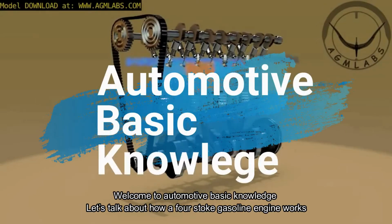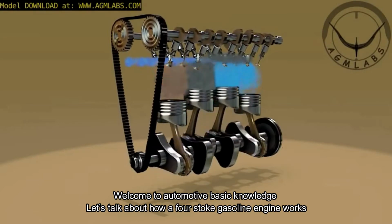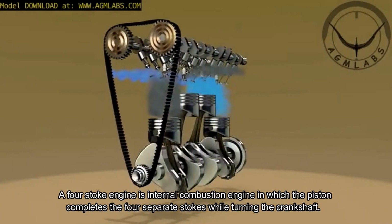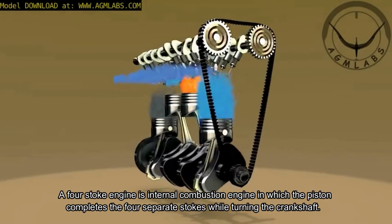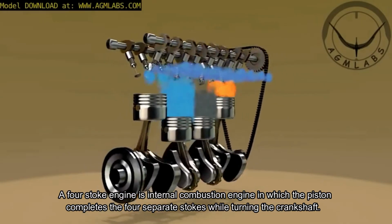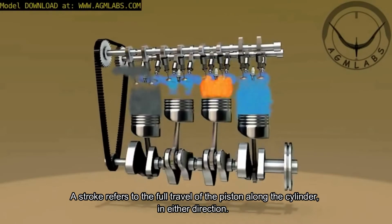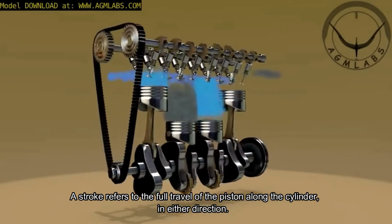Welcome to Automotive Basic Knowledge. Let's talk about how a 4-stroke gasoline engine works. A 4-stroke engine is an internal combustion engine in which the piston completes 4 separate strokes while turning the crankshaft. A stroke refers to the full travel of the piston along the cylinder, in either direction.